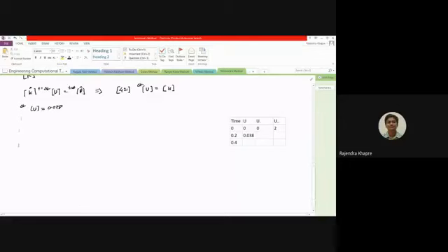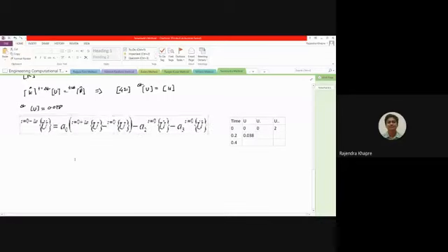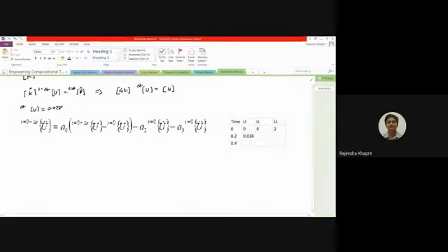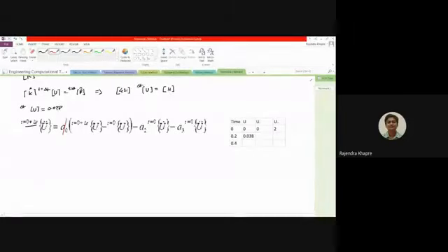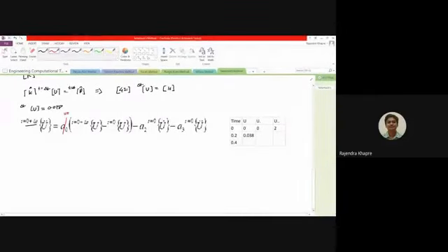For calculation of the acceleration, the equation is given to you. It is something like this. So this is the acceleration at t plus delta t. This is not printed properly, so this is plus delta t. Here we have to find the value of a0, which we have already calculated as 100, and this is the value of displacement at delta t. The displacement at delta t, we have just calculated as 0.038.